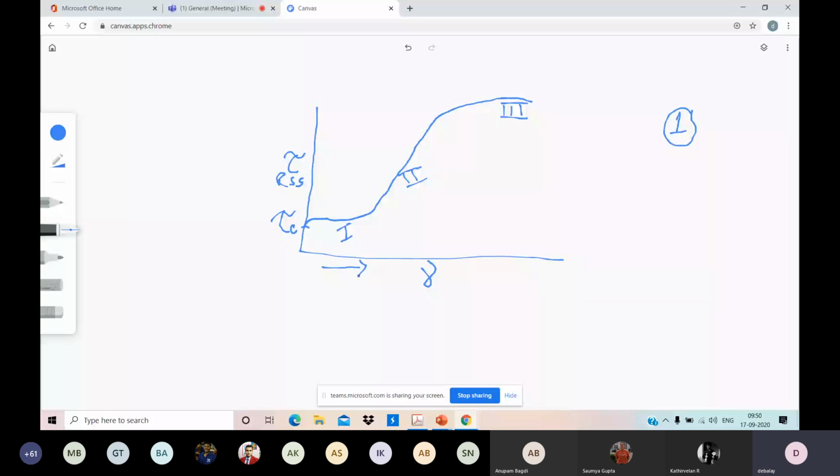Then as a dislocation moves, as deformation occurs, from one dislocation more dislocations generate. This is called dislocation multiplication. Like a virus, when it goes inside the body, it produces millions of replicas. So more and more dislocations will start forming and moving, and more deformation. That is why you are getting more permanent deformation strain.